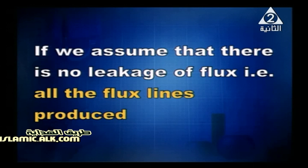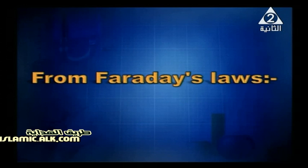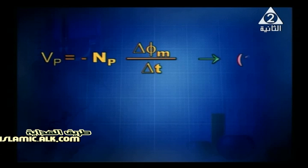If we assume that there is no leakage of flux, that's to say, all the flux lines produced by the primary coil link the secondary, and the coils have negligible resistance, we can say from Faraday's law, the EMF induced in the primary, denoted by Vp, is equal to minus Np delta phi magnetic over delta t.